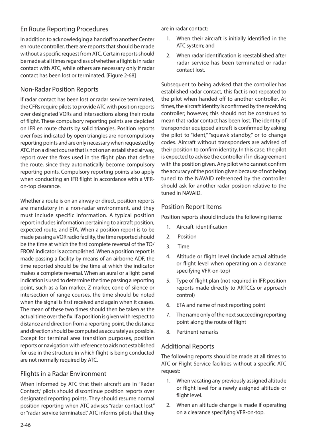If radar contact has been lost or radar service terminated, the CFRs require pilots to provide ATC with position reports over designated VORs and intersections along their route of flight. These compulsory reporting points are depicted on IFR en route charts by solid triangles. Position reports over fixes indicated by open triangles are non-compulsory reporting points and are only necessary when requested by ATC. If on a direct course that is not on an established airway, report over the fixes used in the flight plan that define the route, since they automatically become compulsory reporting points.